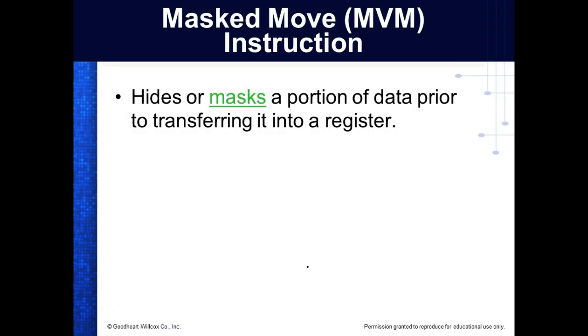Mask, because this is move with mask, and we talked about this. Move with mask allows us to strip off bits. So we looked at AND. Everybody understand what an AND does? What do we do with an AND mask? It has to have two truths to make a true output, right?